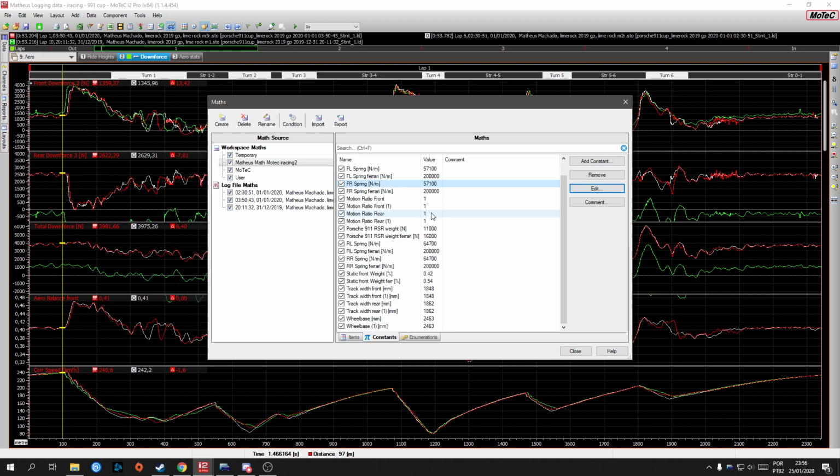But as soon as it's completely compressed with the car load, it shouldn't have an effect. But iRacing takes that it's working as a series throughout the whole suspension travel. So basically, the car has a softer spring than it should have if it was correctly simulating the real-life behavior. But to get the downforce values making sense, I noted that, and that's fine. I guess that's an approximation they wanted to take, and I think they had way more data than I have to compare the real car to the simulated car.